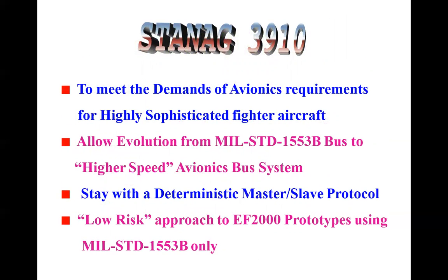Here it meets the demands of avionic requirement for highly sophisticated fighter aircraft, allows evolution from MIL standard 1553B bus to higher speed avionic subsystem, stays with a deterministic master-slave protocol, low risk approach to EF 2000 prototype using MIL-STD-1553B only.